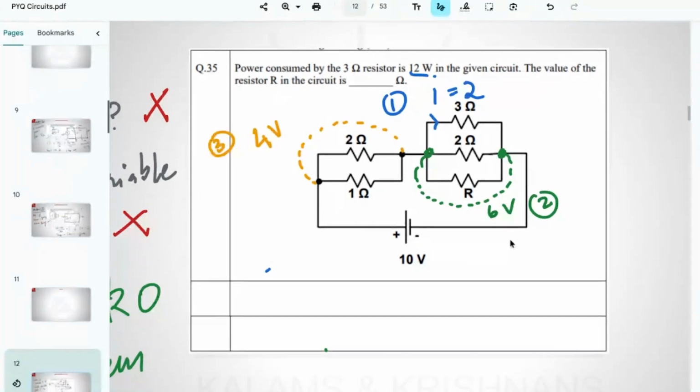That is step 3. There is a 10 rise. There is a 6 drop. It has to be drops, okay? Current cannot be in different directions in this resistor. They are all parallel. Only the magnitudes change. Direction remains the same. Higher potential on the left hand side, lower on the right hand side. Current flows from this side to this side. There is no question about it. Okay, so there is a 4 volt drop there.